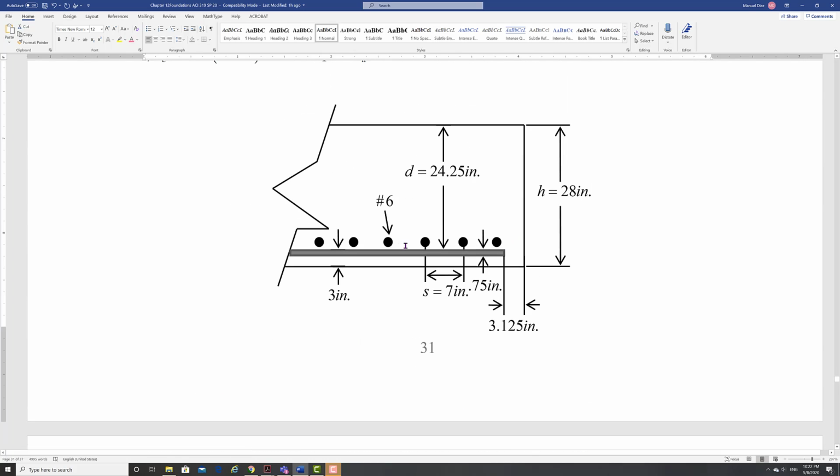When I put in my bars, approximately at 7 inches, number 6 is both directions. I didn't do the other direction because that direction has less length, so I'm okay on that direction. I already checked that. So that's the nice thing about having a square footing. Otherwise, you need to design the other direction. More work. It's double this number of pages.